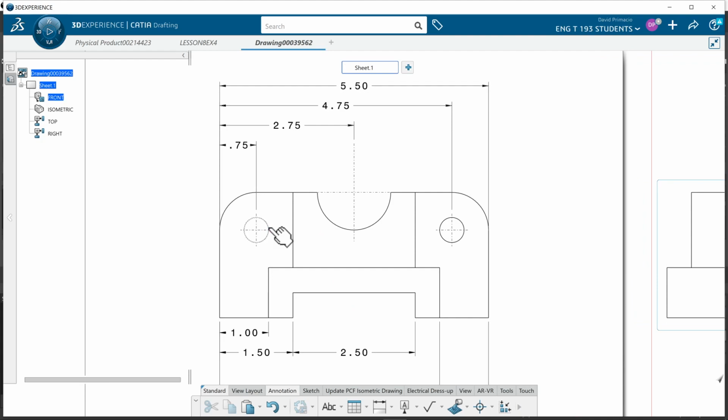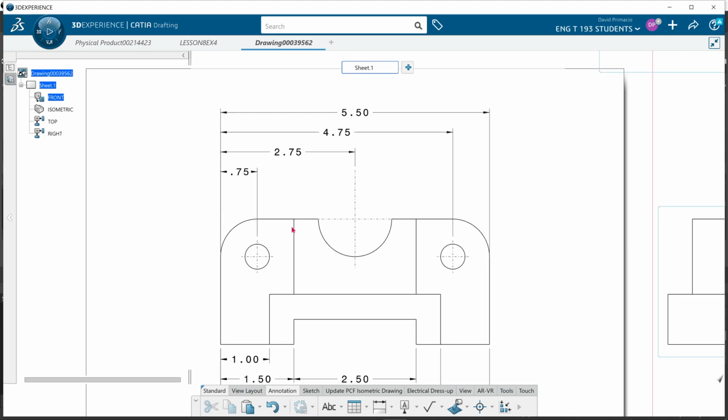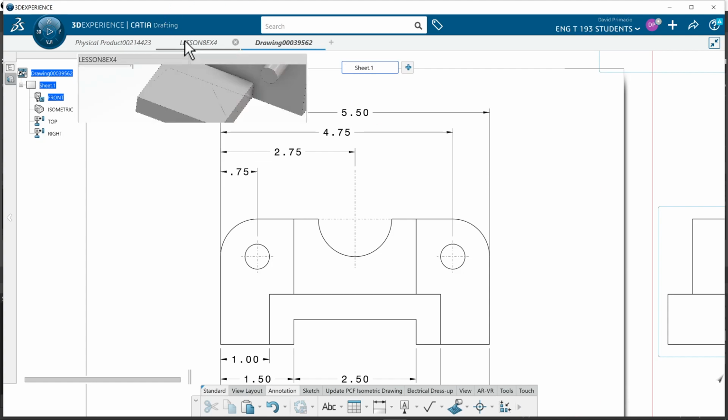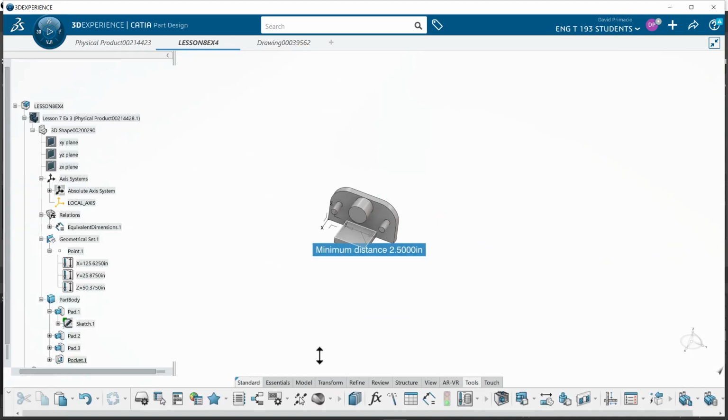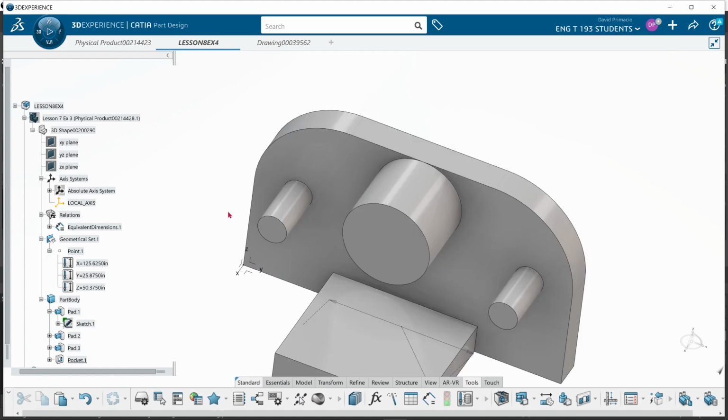Now also just as critical here is I need a dimension from this hole to this hole, because this number here is 0.73 and this number here is 4.78. I'm still within engineering tolerance according to how I dimension this. Well, that's going to be a problem when I go and try and line up these holes to these two pins sticking out.